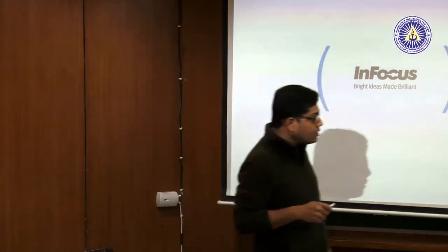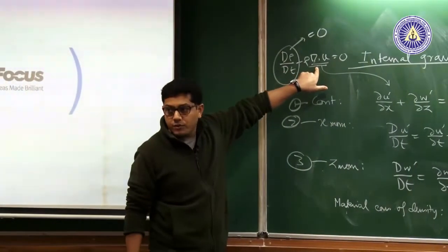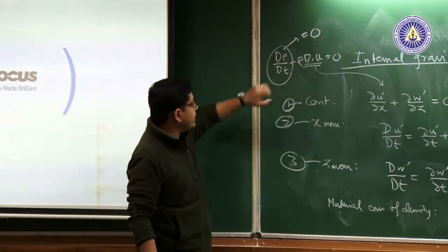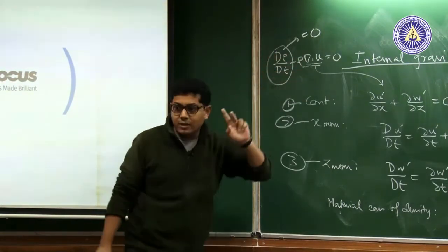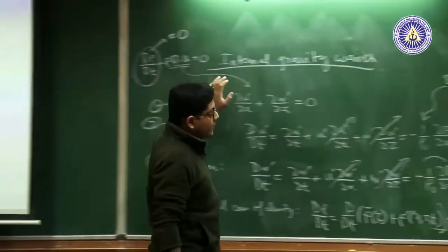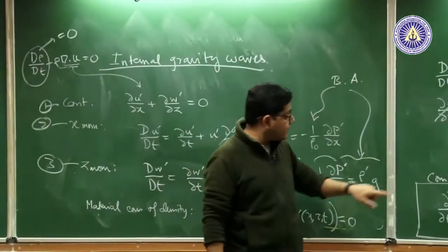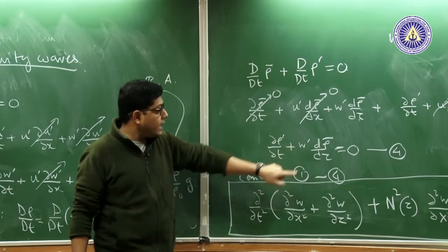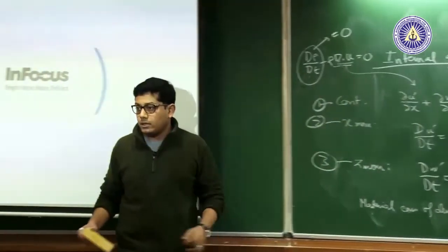Anyways, D rho Dt as 0, which individually makes divergence of u also 0, because the flow is incompressible and the divergence free condition is satisfied. So D rho Dt being 0, the one equation can give rise to two conditions. One is this material conservation of density, from which you get a direct relation of rho prime with w prime. And the other is the continuity, what you get in general.